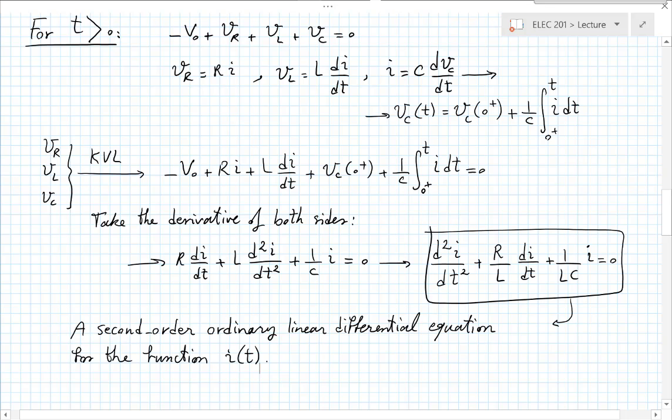Maybe let me ask another question. Imagine for a second I put R equals 0. So if I replaced in that circuit my resistor with a wire, so R equals 0, no resistance, and I followed everything else, I would get the same equation, but with R equals 0 here, which means the middle term would disappear. So then I'd have a second derivative of I plus some parameter multiplying the function I itself equals 0.